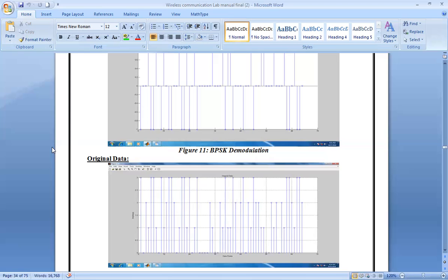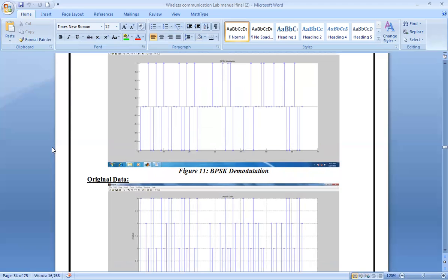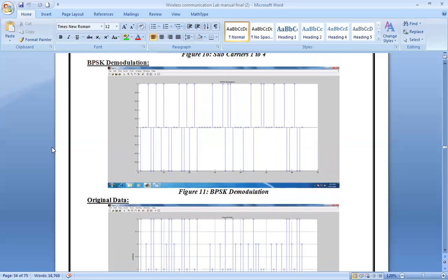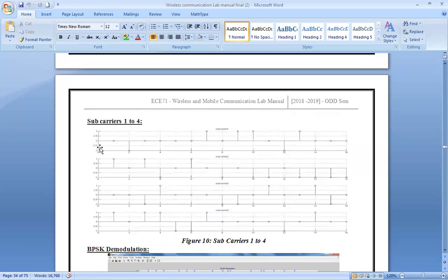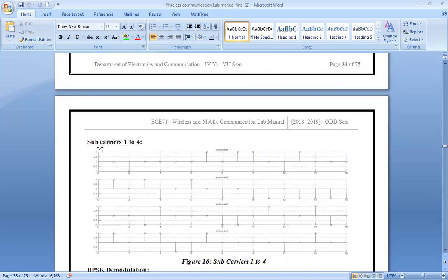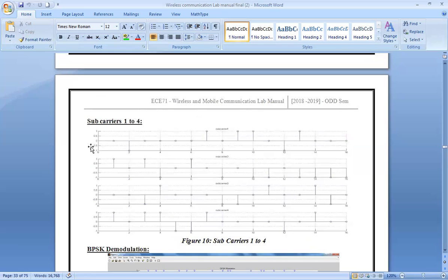The operation outputs the complex envelope of the modulation of the message signal using PSK. Then S2P, the serial to parallel converter: don't use semicolons there when you are doing S2P, so that the output can be seen at every step. If you use that semicolon, you wouldn't be able to see those conversions happening.